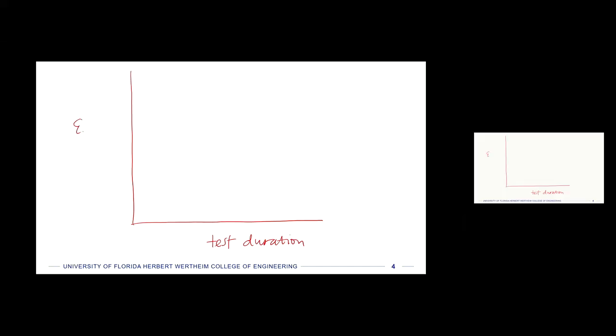So I'm just going to call this sigma or epsilon creep, CR, and a test duration. And then we're going to have these be isothermal, so the same temperature for all of them. And then what we're going to do is apply different levels of stress to the part.